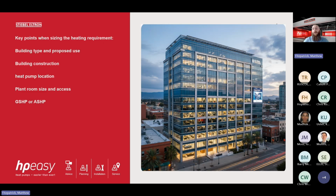We also need to look at how the building is being used. So a standard office block may have 100 offices, but at any day in the week, only 50, 60, 70% of those offices may actually be occupied. We would still need to specify the heat pump size for the full capacity of the working load of the building. So all 100 offices in use at the same time. Same for domestic hot water. We need to keep in the redundancy.